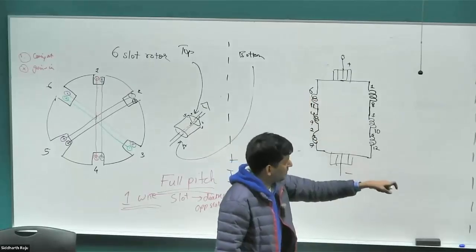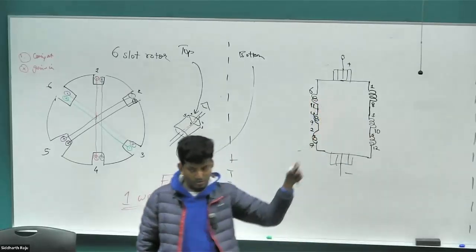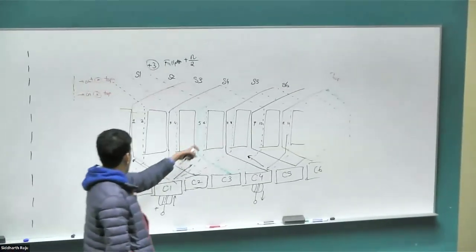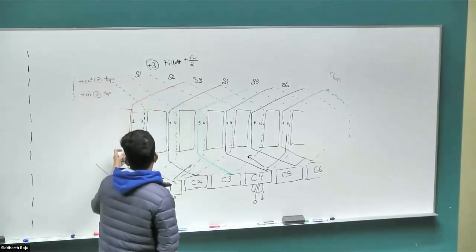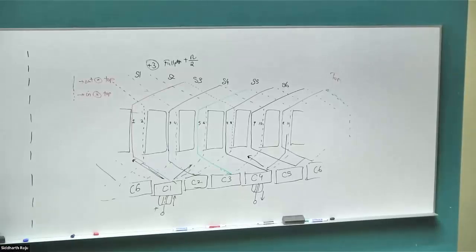And then we need to double check that 6 is actually what is terminating on the brush outside, which is exactly what we have here. So conductor 6 is the one terminating on the top brush. Again, if you trace the path backwards too, it works either way, just a little bit more confusing.